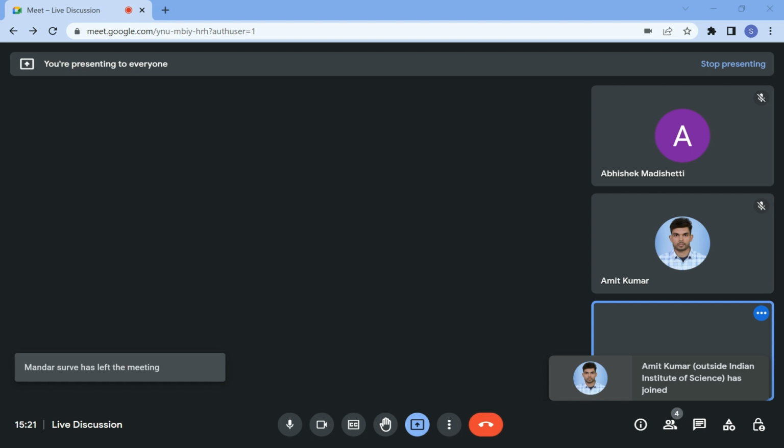Now I will change the color. Let us go for green. So the second condition is that this line AB is at 45 degrees with respect to the vertical plane. The angle with respect to the vertical plane is seen in the horizontal plane in top view. So let us have an XY plane here. To avoid confusion, I'm drawing it here, but this point A, when you actually draw it, you should draw it together. This is point A.